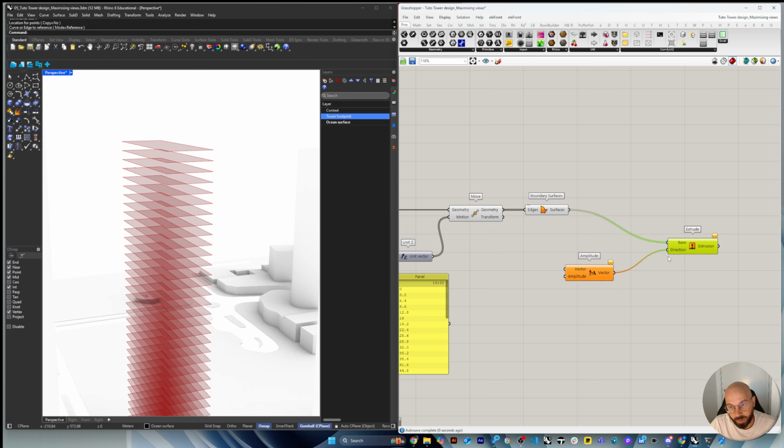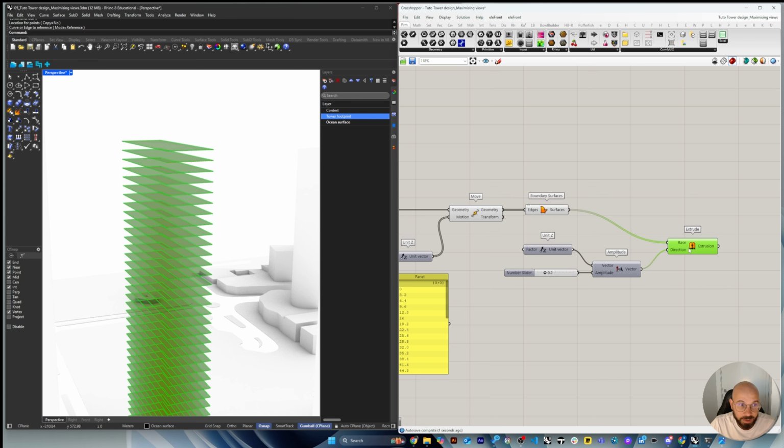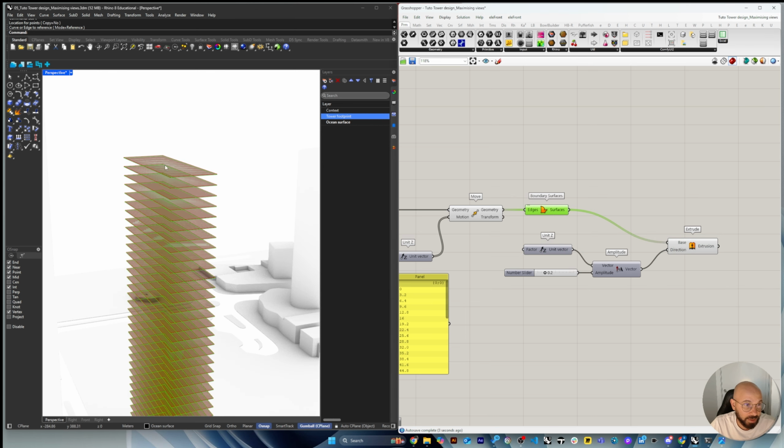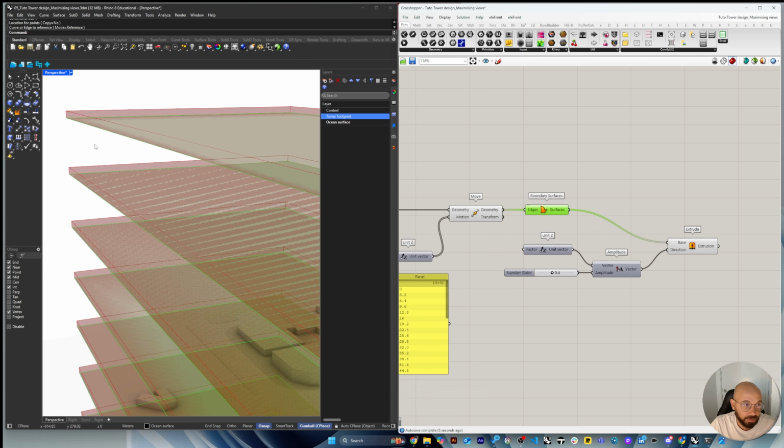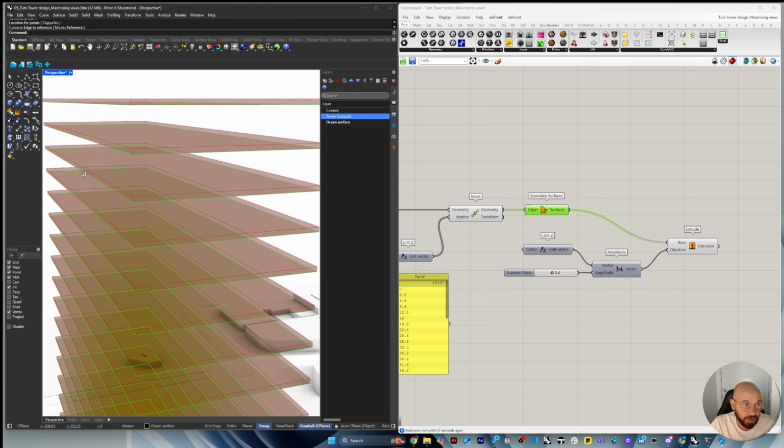And we're just gonna plug our vector here, and then the amplitude we're gonna say 0.2 for now as a slab thickness. And then the vector, we're just gonna say Z vector. But I always like to keep the surface at the top. So then if you need to increase the slab, it will not reduce the area here and make it very confusing.